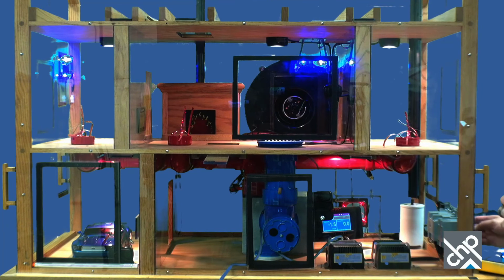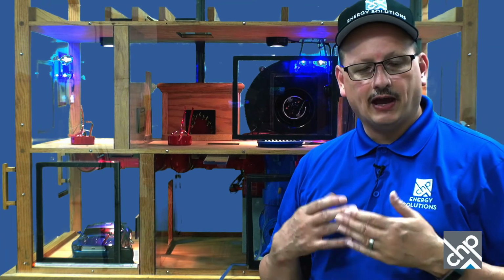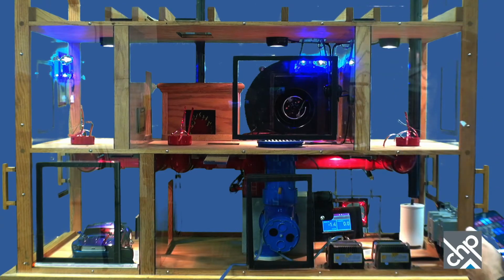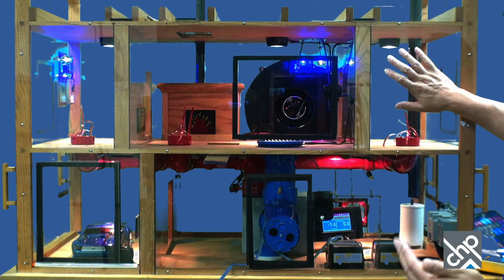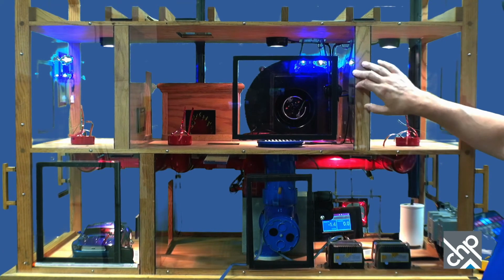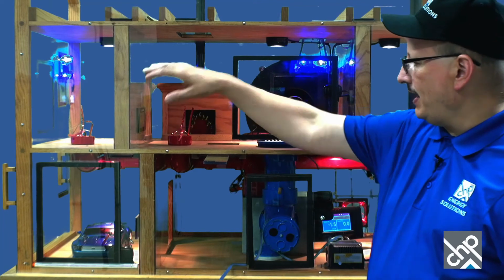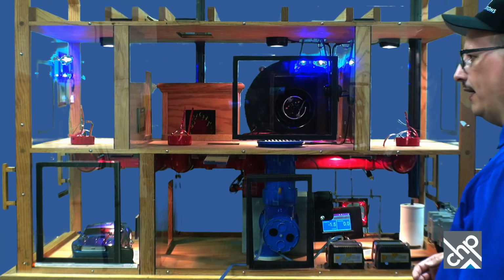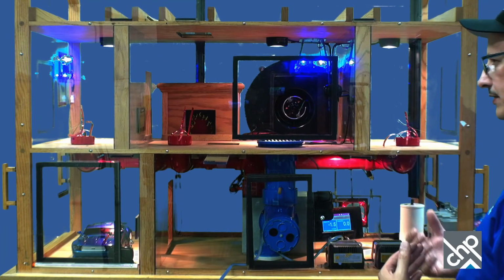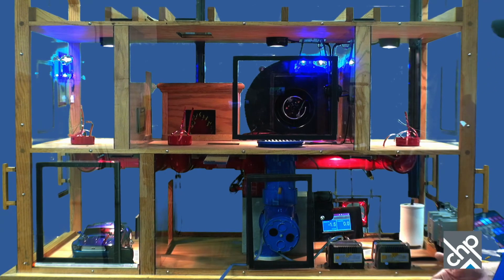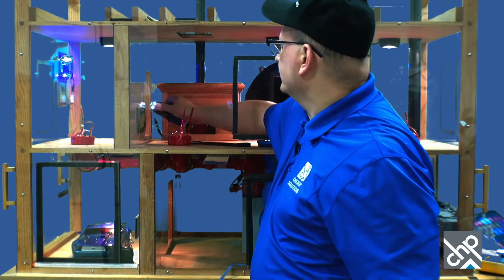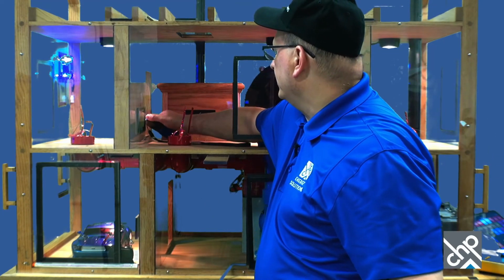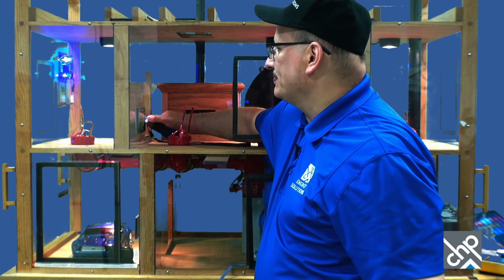All right. So now we have all those fans on. That's where we left off. We've got all the exhaust fans on. Now we need to check the doors, right? So I've got the doors up here. This again is the bedroom door. There's no fans behind it, so we don't need to check that one. This one over here has a fan behind it. We would smoke it and see if it goes under the door. And I'll go ahead and do it again. It won't take me but a second. I'm not going to zoom in, but you all can trust me. It's actually pulling the smoke in.